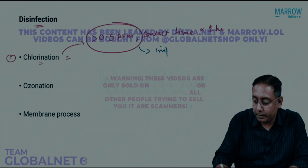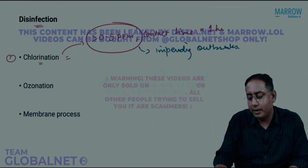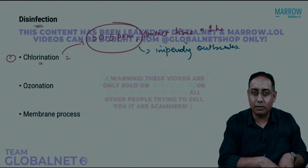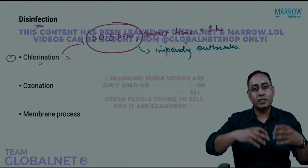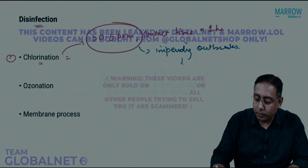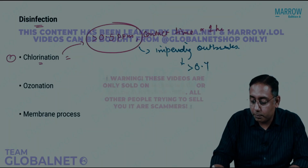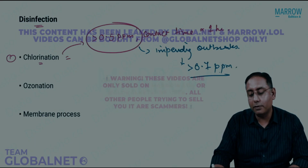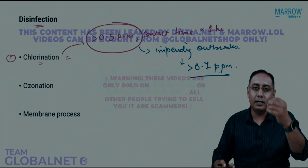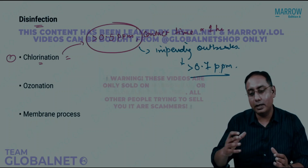In case of impending outbreaks, where you think that people will be getting together, there is some religious mela, some religious get together, or some festival coming, and you feel that there could be some outbreaks, the government keeps the chlorine to be more than 0.7 parts per million. But of course, all said and done, this is only for MCQs. In real time, usually it is more than 0.9, even more than 1 ppm of chlorine level when there is an impending outbreak.